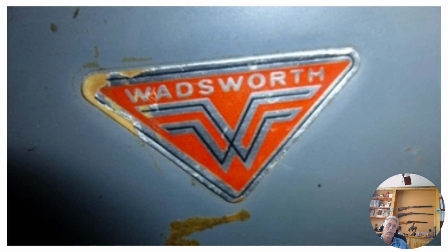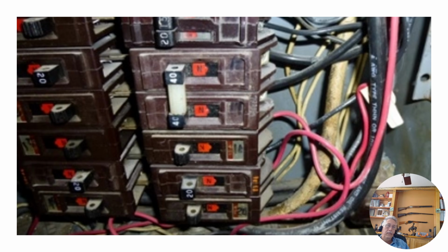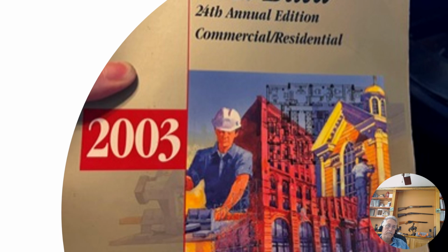If it's that old, this is probably from the 50s, it's going to be written up. And you can find information about them causing fires online, along with FPEs, Federal Pacific panels. There's a shot of the inside. Plus, you can't find new breakers for them, replacement breakers.